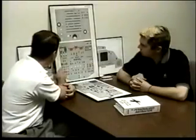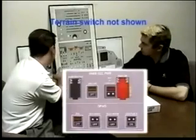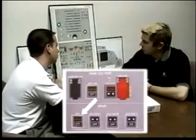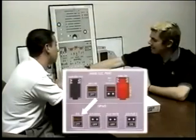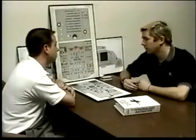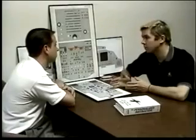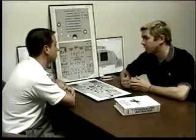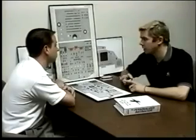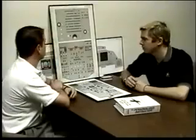GPWS. To the left, on some aircraft, some models, you have a terrain switch. Describe to me that terrain switch and the system switch for the GPWS. Okay, the terrain switch is for the eGPWS only, and that's basically an on-off switch. If I select it off, I lose eGPWS capability, but I do not lose GPWS. When I select that eGPWS switch off, I don't have the pop-up feature, I don't have the terrain on ND, I can't get any of those features. But GPWS still works 100%.